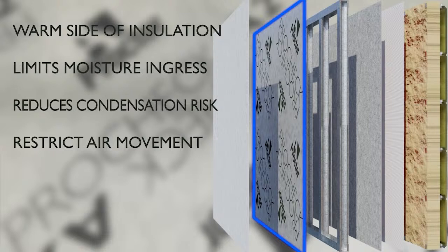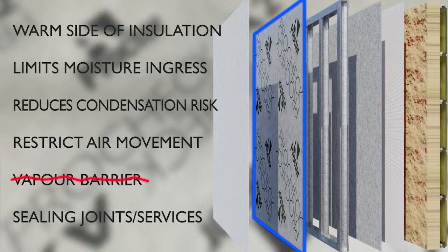It used to be common to refer to AVCLs as vapour barriers. However, this terminology implies they are 100% effective at preventing moisture flow, which is rarely the case. Fixings, jointings, and detailing, as well as service and structural penetrations, will all affect their effectiveness, even in high-quality installations.